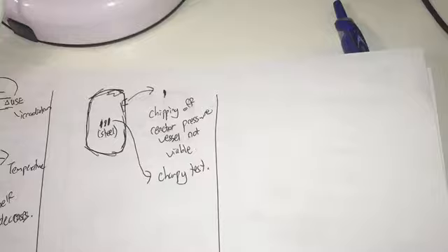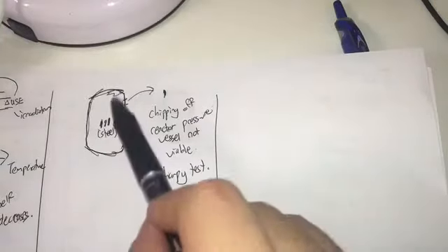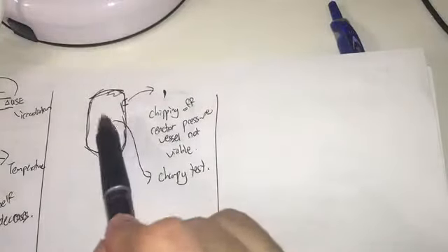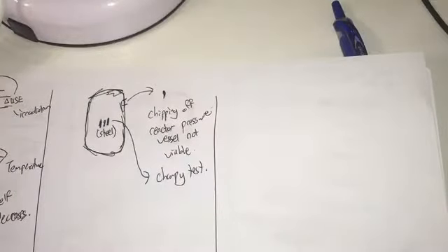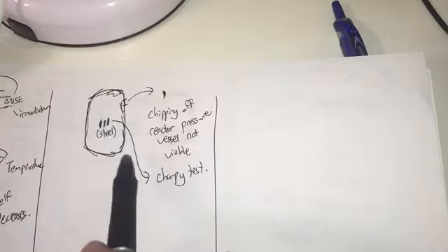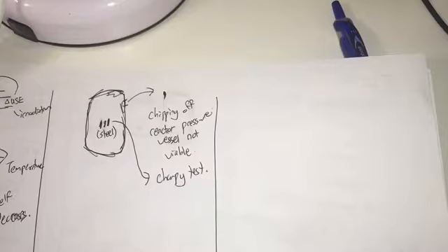Now you can monitor the radiation damage of the reactor pressure vessel by taking a representative lump of steel inside the center of the core, where it's receiving even more radiation, so that it's a conservative estimate of how much radiation damage there is. So you can monitor the radiation damage of the RPV and test in advance how it reacts to thermal shock every now and then.